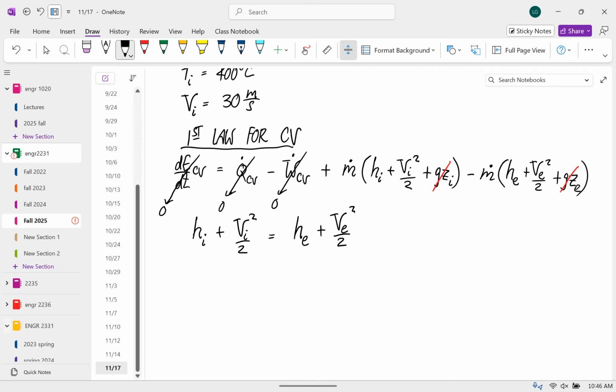And for water, we can look this stuff up. That's a good question you asked about ideal gas. It is a vapor the whole time, it looks like. So you could probably do this and get okay results for an ideal gas, but I did just use the table or the website for this. Because we were given the fact that it was at saturation, which means we only need one property to determine the rest of the properties. Right, that's right.